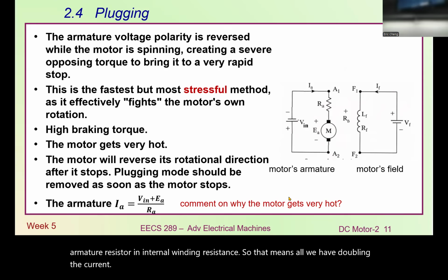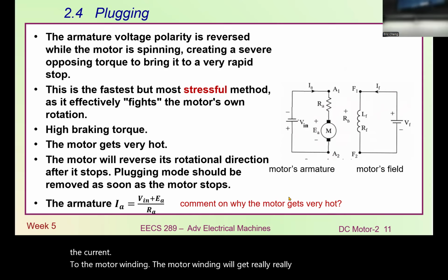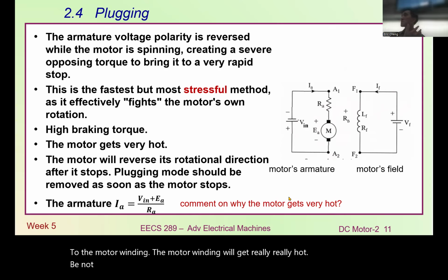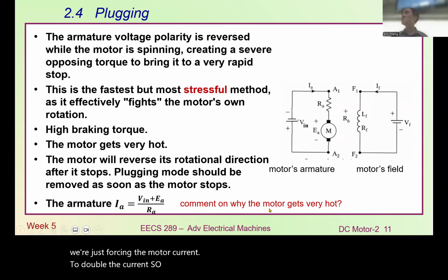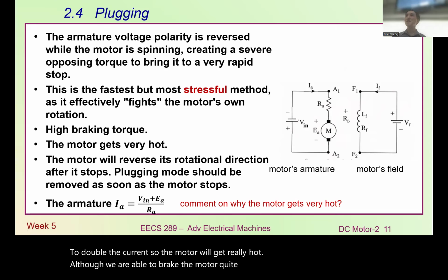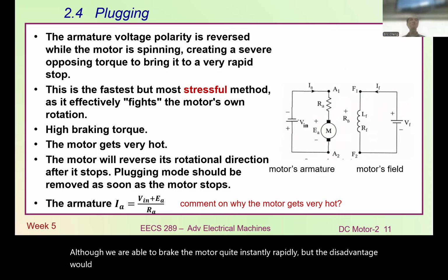The motor winding will get really hot. We're not transferring energy to a DC source, back to the battery. We're not doing that. We're just forcing the motor current to double. So the motor will get really hot. Although we are able to brake the motor quite instantly, rapidly, the disadvantage is that we are damaging the motor.